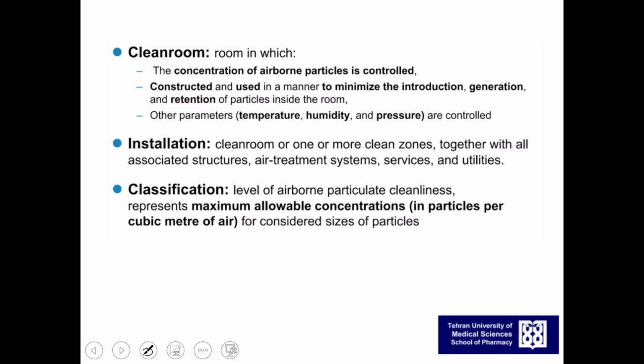We have divided the clean room as per the ISO standard or USA or European standard. So we have nomenclature like class 1, class 10, class 100, class 1000. It depends upon the particle count per cubic foot available in the clean room. That means if it is a class 1000 clean room, 1000 particles per cubic foot will be acceptable in that case.